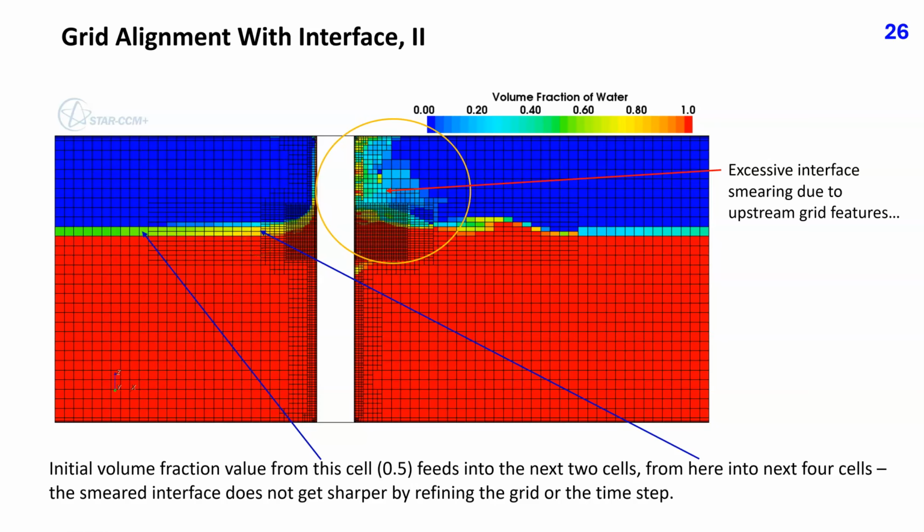The best solution is to adapt the grid to the initial free surface or to avoid local grid refinement in the vertical direction near the free surface. This increases the cell count but ensures that such problems do not arise.